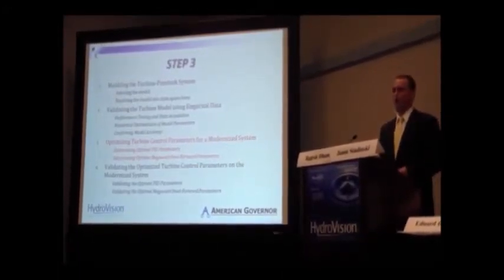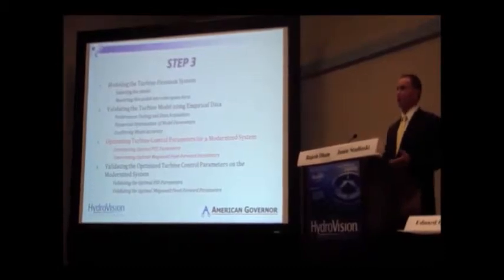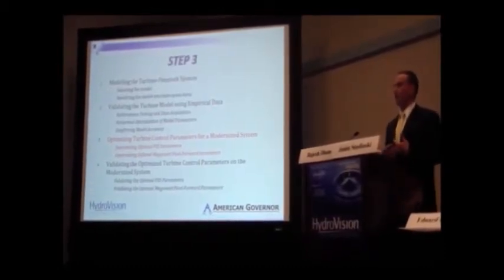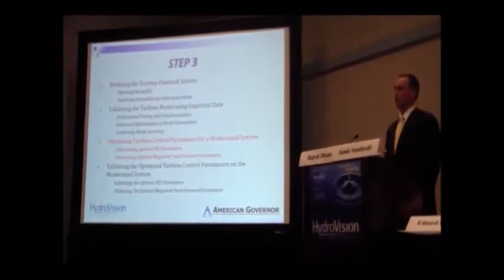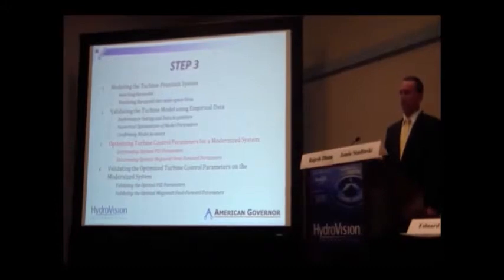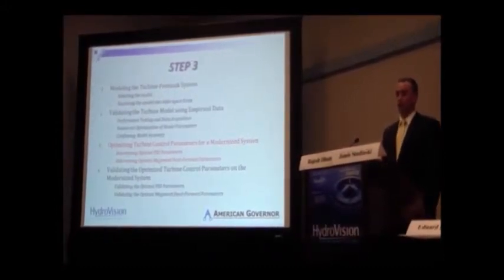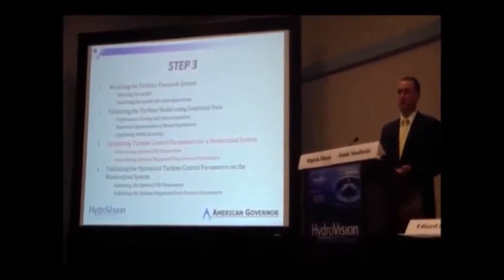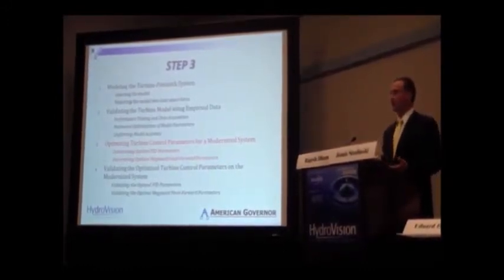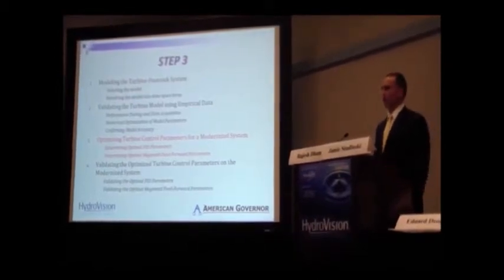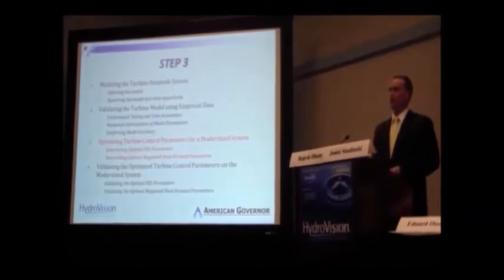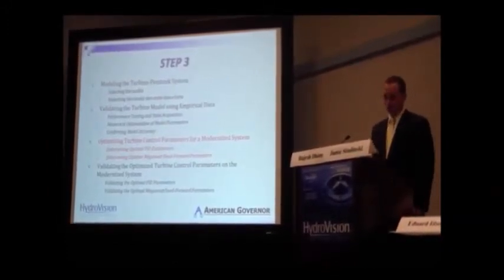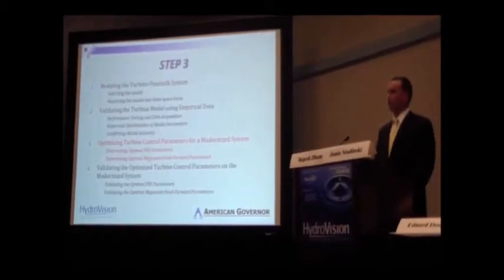We can take this model and put it through the ringer. We can give it step changes. As the governor guys, we're concerned with speed stability. We're concerned with how you can load the units. And in this case, we can sit in our office essentially long before commissioning, long before we have to schedule major outages or deal with any of those considerations, and play around with the system and tune those PID parameters and our underlying control parameters ahead of time. And additionally, when we're online, we have some methods of primary power control, which we also could tune in and see how it conforms.